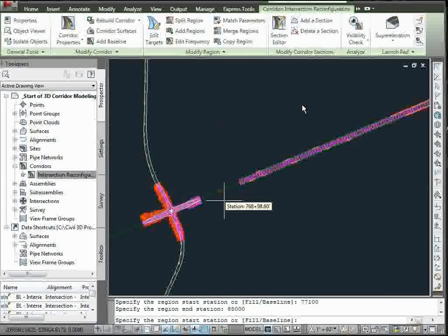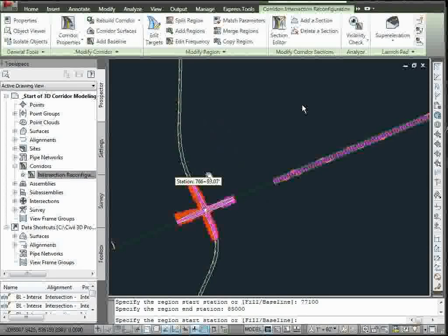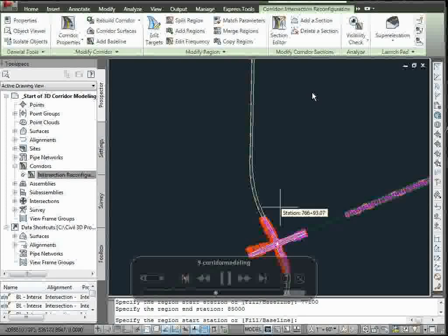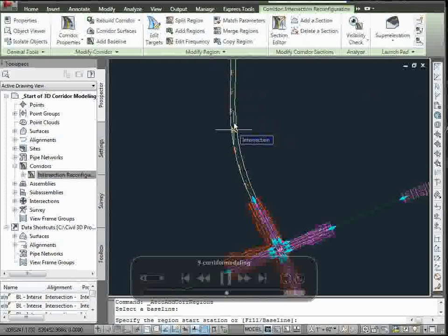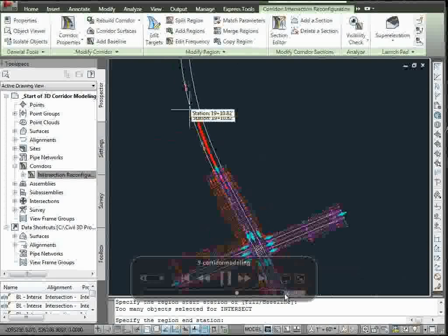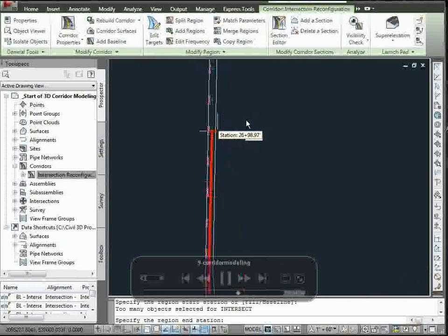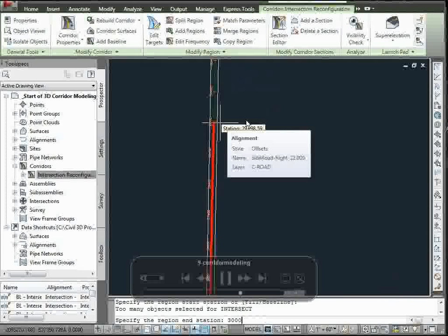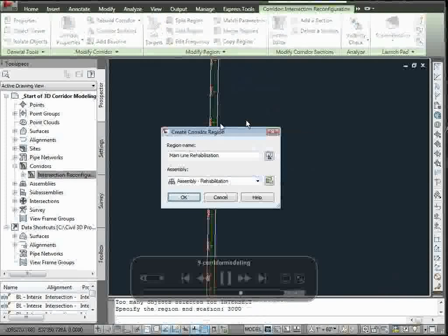So what you see right here, just as quick as that, we grabbed the geometry and we created that northeasterly piece of roadway. We're going to do the same kind of thing now, simply with the northerly piece. And I'm going to move up on this a little bit quicker. So we grab it, and the one difference here is that we're going to need to select left and right widening. We just simply, with a data button, connect to this, drag the roadways, and what this lets you do, instead of getting in that tab and having to key it in, you can either key it in at the command line or drag the thing where you want it and do what-ifs.